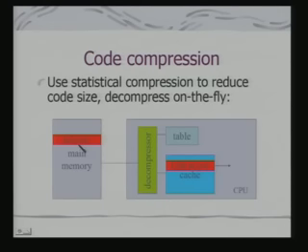The actual instruction can be 32 bits, but my representation can be 8 bits. In fact, I can use any form of entropy coding, a variable length coding, for instruction compression. A very common example of this, if you remember, we had discussed use of Java, J2ME. For J2ME you use an archival format of the code and not the standard format, where the binary code is actually compressed so that it can be loaded onto a small memory in the embedded system.